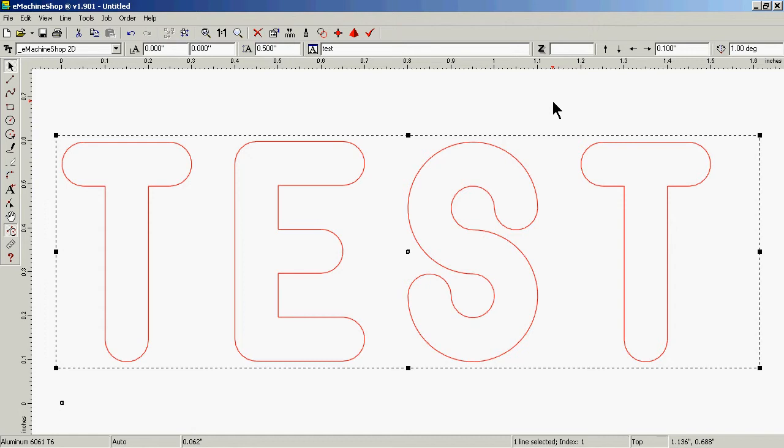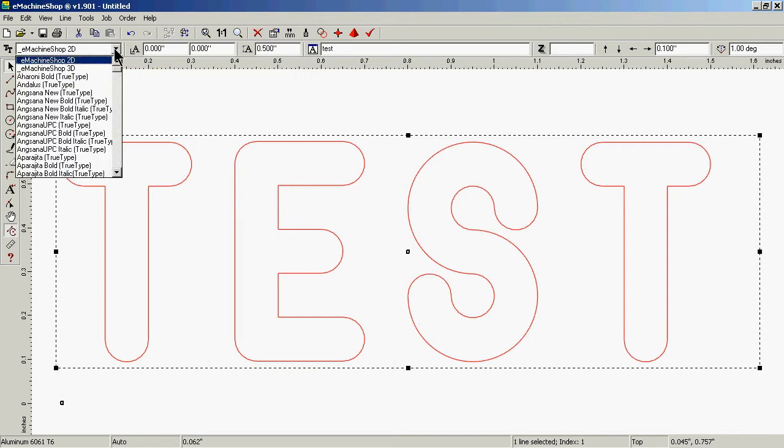If you don't, then it's going to come on the screen as a comment to the machinist, which isn't a problem. You can reselect the text and then go up to the top and click auto. Since there is text already there, you won't get an error. Once you're in the auto mode, this setting is the only place that you can actually pick a font. You pick your font from the list over here on the side, and it'll then convert the font for you.